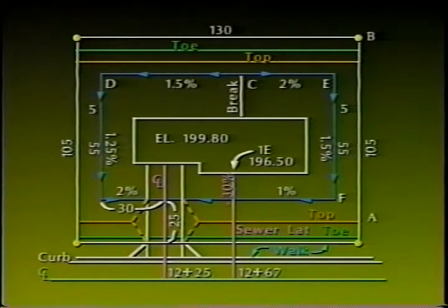From the street section, we find that there is a 0.33 foot fill from the center line to the back of the walk. Adding 0.33 feet to the center line elevations for each station will give us the answer to question 1.